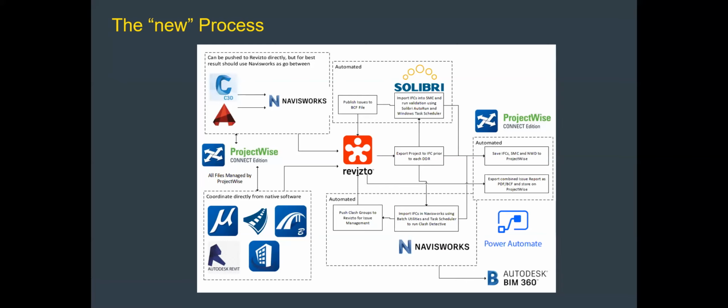Stuff like MicroStation, OpenRoads, OpenBridge, Revit, and OpenBuildings doesn't necessarily need to go through Navisworks because those exporters maintain the metadata around what the object is. So it'll include things like an asset identification, the Uniclass classification, and other bits and pieces into Revizto.